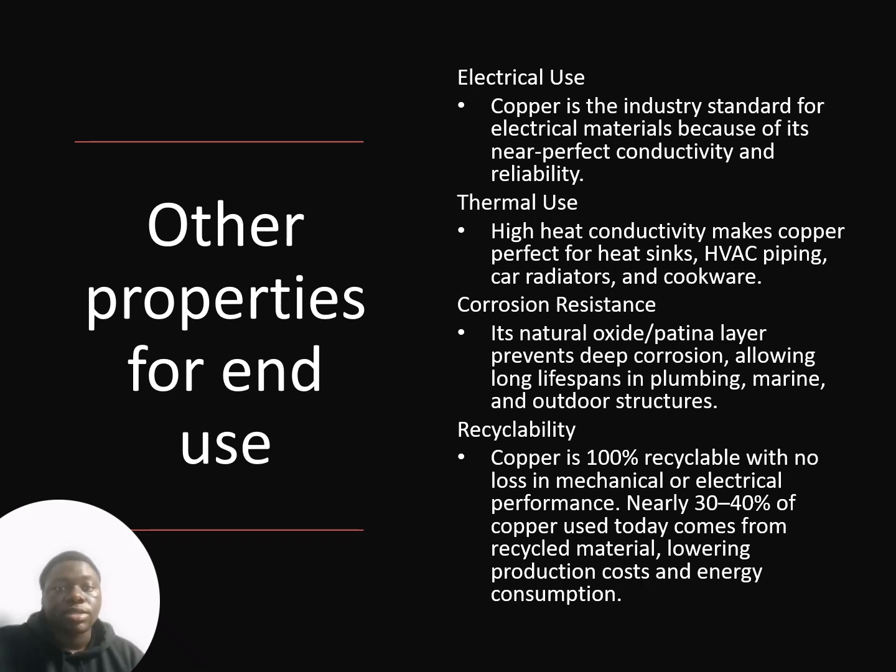Corrosion resistance. Its natural oxide patina layer prevents deep corrosion, allowing long lifespans in plumbing, marine, and outdoor structures. Recyclability. Copper is 100% recyclable with no loss in mechanical or electrical performance. Nearly 30 to 40% of copper used today comes from recycled material, lowering production costs and energy consumption.